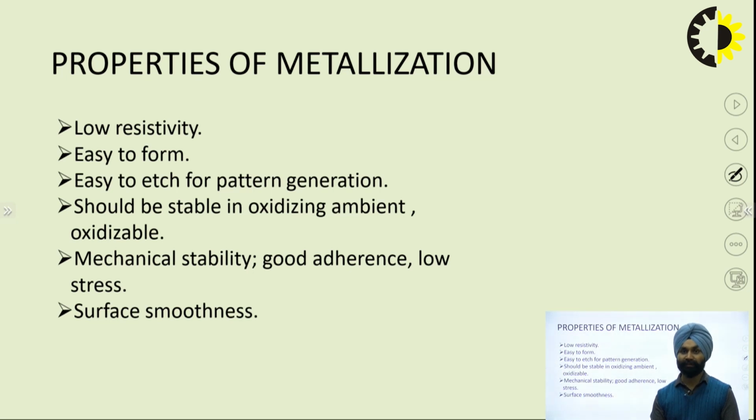The first property is that it should be a metal with low resistivity, so that low resistivity will provide good contacts, plus there will be no heating due to the resistance. So with the low resistivity, our purpose of the metallization will be more predominantly followed.